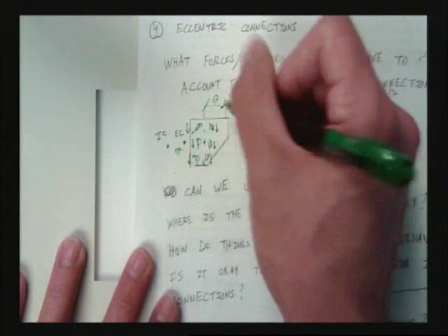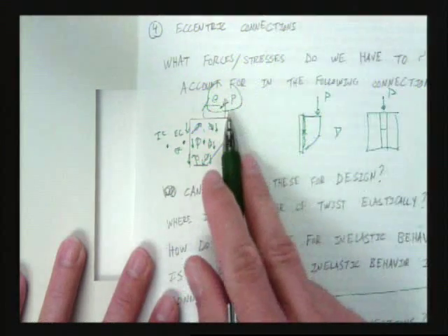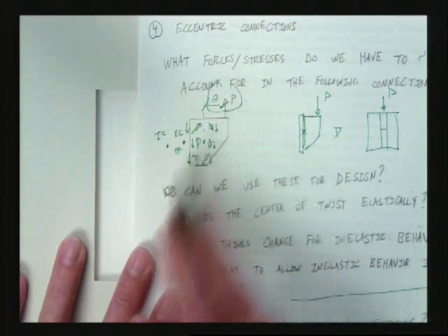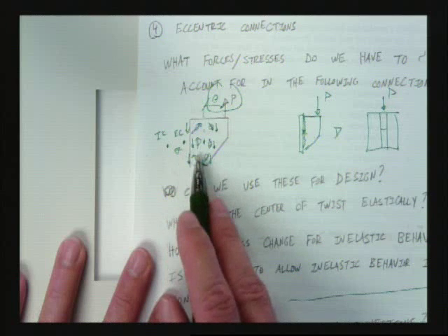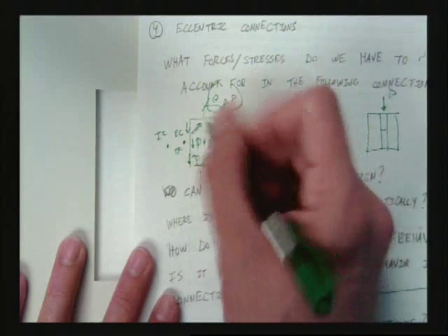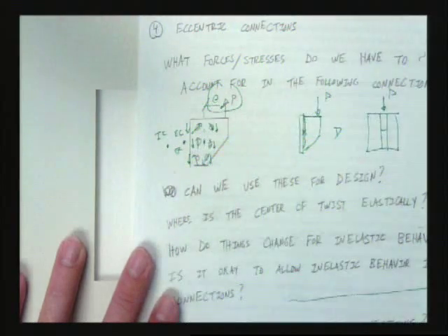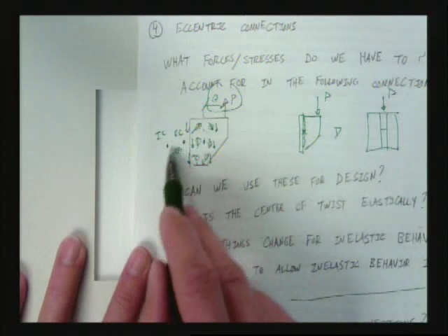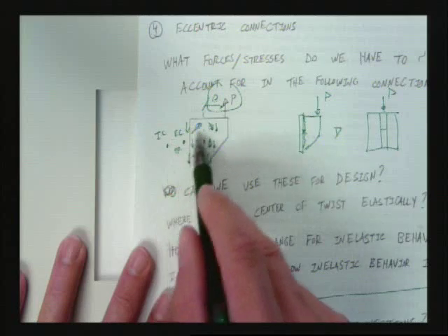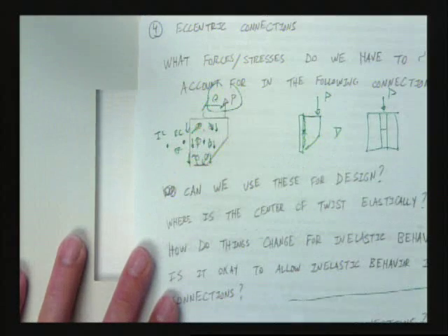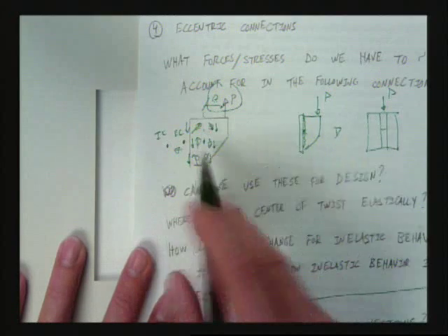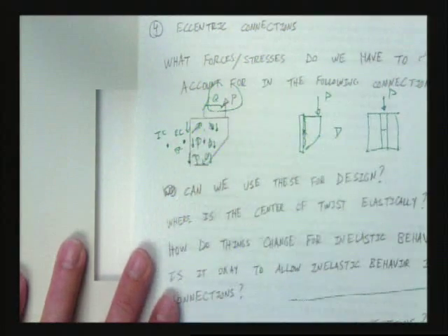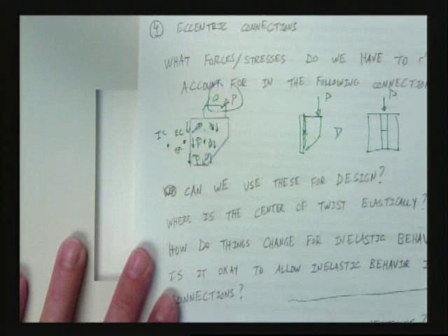Okay? And then you have to look at the moments applied externally, and then you have to look at the moments applied internally. They have to balance. Where you're assuming every one of these bolts are at their limit. Okay? So if you assume every bolt's at their limit and you assume an instantaneous center, now you know the orientation for each one of the force vectors on the bolts. They have to be perpendicular to the instantaneous center, right? So you solve that internal moments have to be equal to external moments. You're with me? So what happens if you find out they're not?